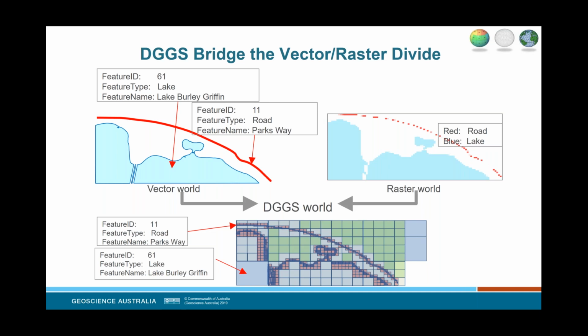And another point, which is probably more important and more alarming, especially when you're dealing with polylines, is that if you don't get the rasterization process right, and the scale and the resolution that you've decided to rasterize your vector at, then you break it up. And so you go from this nice continuous feature here on the left to this blocky, separated and disaggregated connection.